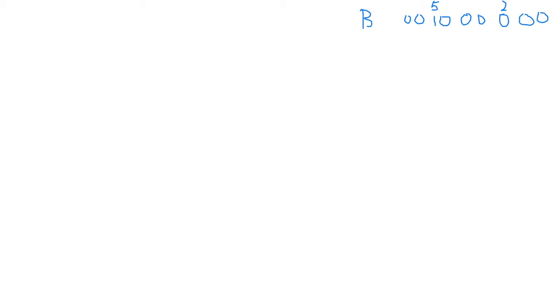Then in order to do the pull up, we achieve two things. We switch the LED off, and at the same time, we set the input pull up by connecting the port. So this is port and this is the data direction register. We set that particular pin to 1 because it's an input. If it's an input and you send a 1 to it, you are just connecting to the 5 volt source.